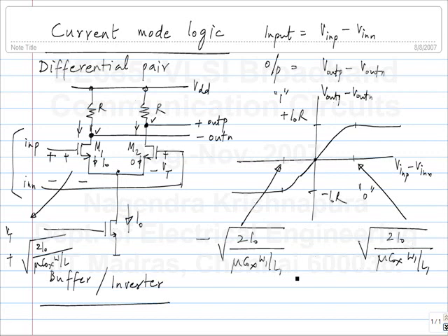If you look at any logic, you need gain in the logic circuit. The level difference between the logic levels at the output should be more than that at the input, because the assumption is that you have similar gates driving each other. If you drive a gate like this using another gate like this, the levels of that must be definitely sufficient to swing the logic of this.